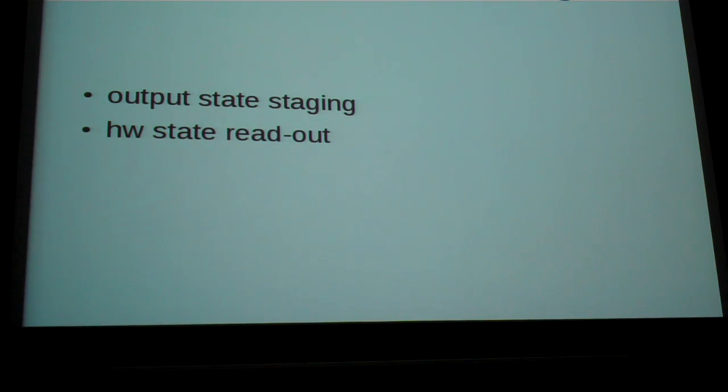And the nice benefit is that we can use these functions to cross-check software and hardware state. So after each mode set, we run through all these get hardware state functions and check whether the reality actually matches up with our idea of what it should be, which helped a lot in fixing bugs and preventing regressions, because we had to pretty much rewrite the entire infrastructure, and thanks to the hardware state stuff, that worked out pretty well.